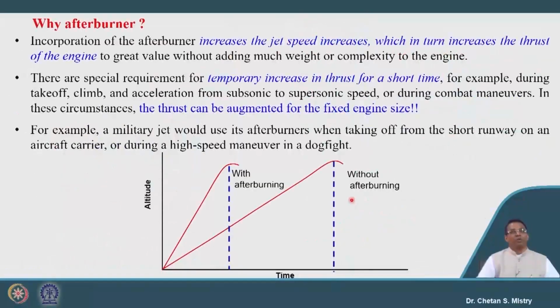Okay. Now if we look at it, the question will come: why do we want to add the afterburner? By incorporating the afterburner we will be able to increase the jet velocity. When we increase the jet velocity, our thrust will increase, and we are able to do this without much addition of weight or complexity to the engine.